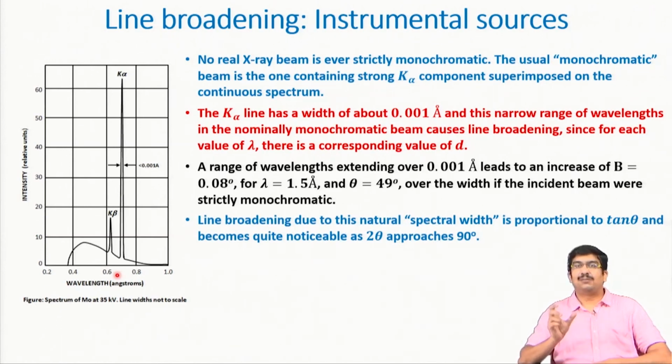It will have a little bit of deviation from the exact monochromatic condition. So, from Bragg's condition, the lambda will change within a range. If we think that d is constant for a certain region, the material is perfect, no imperfection, even with a perfect material, just because lambda is different in the source itself, we will have different sin theta values, and the peak itself will get broadened by a certain amount, a little bit